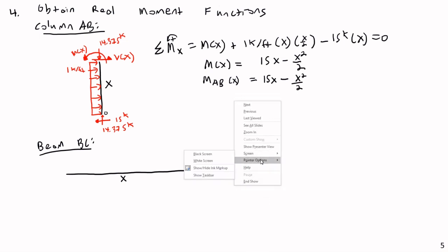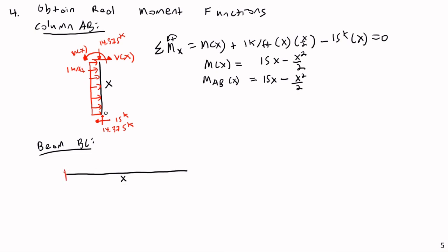So let's look at what forces are on this thing. We have our joint forces on joint B of upward 14.375 kips. Again, remember, I got a negative when we looked at the joint reaction, so we initially assumed it was downward on this member. We had to reverse that because it was actually negative, so now it's shown in its proper orientation.